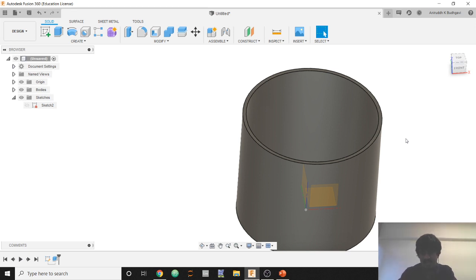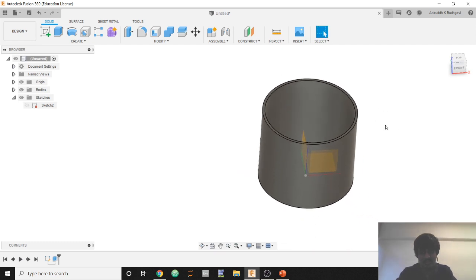So that's what I defined. I defined a circle of some outer radius. I gave it a 5 mm thickness and made a smaller circle. Instead of that, if I just make two circles with different diameters which have no relation to one another, that was the wrong way to go about it. So the bottom line with constraints is, whatever your intention is, translate that into the diagram through your constraints. Let me give you another example of how to use them effectively.